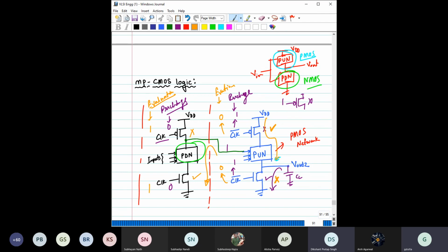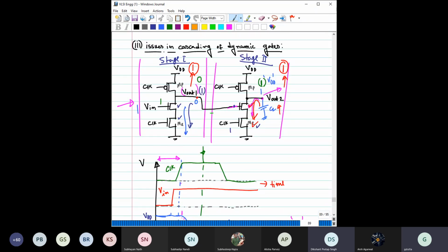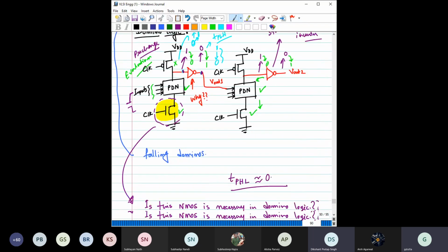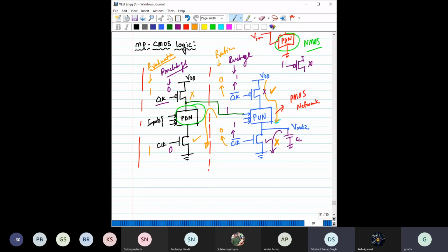The issue was happening there because in normal dynamic logic gates all the MOSFETs were NMOS. So during pre-charge, the pre-charge would also turn on the next transistor. Obviously if it is not an NMOS, if it has a PMOS, that could have solved it. You can guess that from here. So this is the NMOS, NPMOS logic, right?